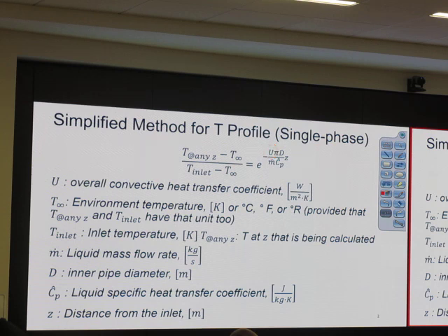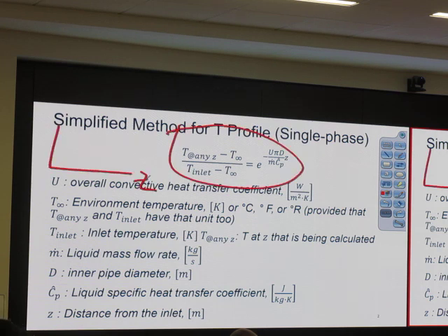When I use the maximum possible U value, I plug it back into that equation. U value means heat loss, right? If we have a high U value, we have a lot of heat loss. If we have a low U value, we don't have much heat loss. When I plot this equation, I get the temperature profile versus distance, like this. It decays exponentially.